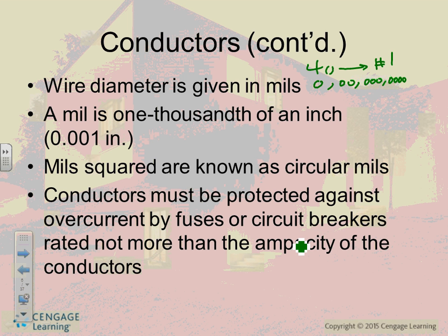That's another range, and then they go 250 kcmil to 2000 kcmil or higher. These are how we ran them in order. So the smallest is 40 AWG to 1, then we go to the aughts, which is 1/0, 2/0, 3/0, 4/0, and then 250 all the way up to 2000 kcmil.